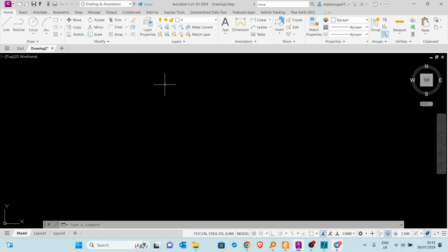So you can set walls into a particular layer so that anytime you want to turn off walls in a drawing, you just turn them off. Anytime you want to turn on doors, which are in a different layer, you just turn them on and turn them off. If you want to freeze a particular layer, or lock a layer, you can do that from the layers tab. The annotation tab is where you do most of your writing.